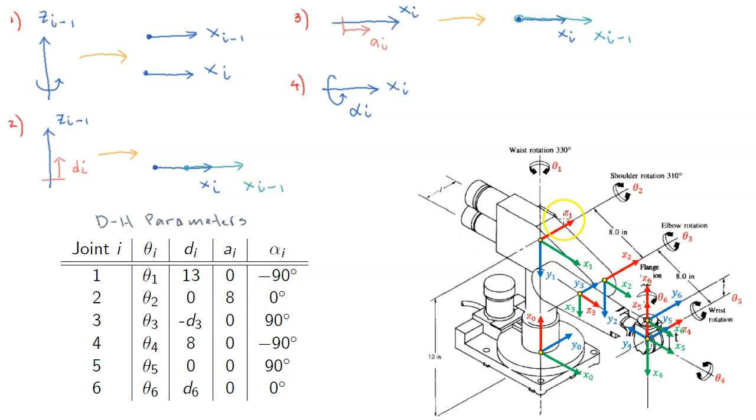Now you can imagine we have this coordinate frame to be here already, and how much we have to rotate coordinate frame 1 about X2 to make the two coordinate frames coincide. The answer is 0 because they are already the same, right? So alpha 2 is 0. Alright, let's look at coordinate frame 3, which is over here.